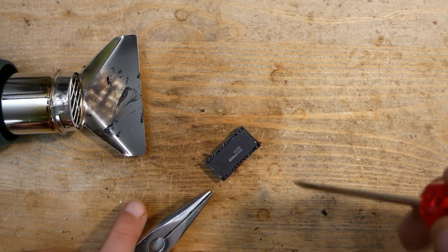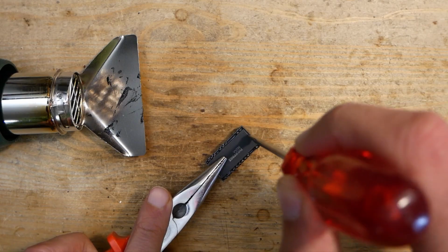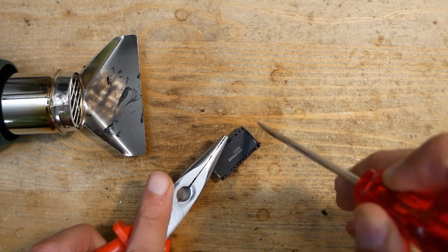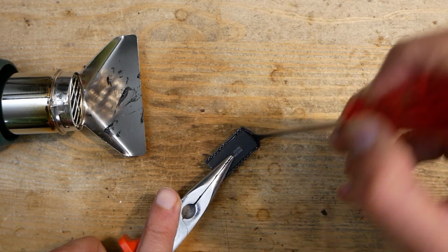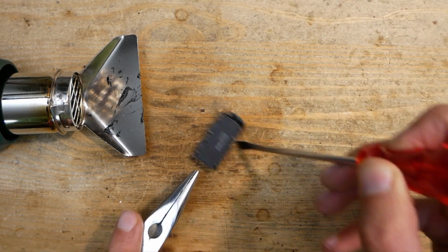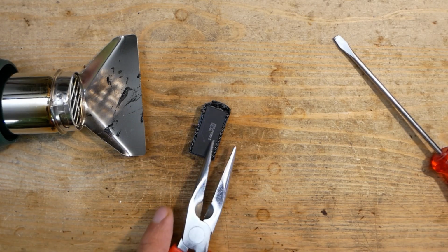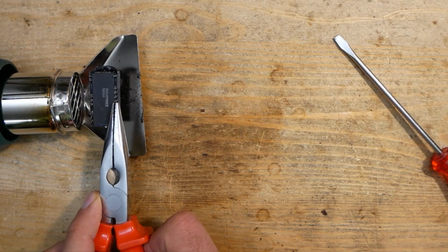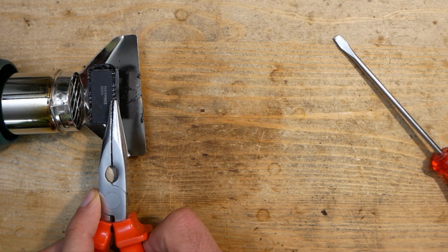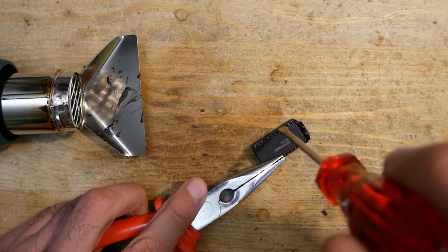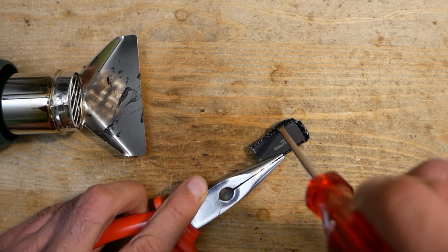So my second try started with reading about resin a little bit. Don't ask why I didn't start with that step in the first place, but it turned out that with rising temperature, resin doesn't melt as I thought before. It actually gets brittle due to a chemical reaction inside. When it cools down, it gets extremely hard again. So armed with a hot air gun, a screwdriver and pliers, I practiced with some of the modules, and after a little bit of practice, it turned out to be child's play.